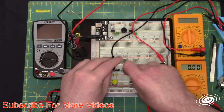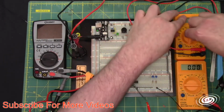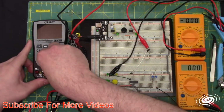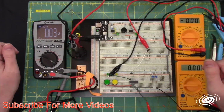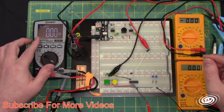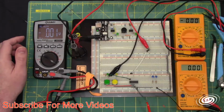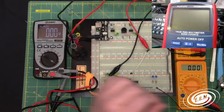And then I'm going to plug in this meter, red to positive, black to the chip. I'm going to set that to 20 milliamps. And then I am going to turn this to DC voltage so we could just probe around and see what the voltages are. Can you see that? I found that this meter shows up better than that meter right there.